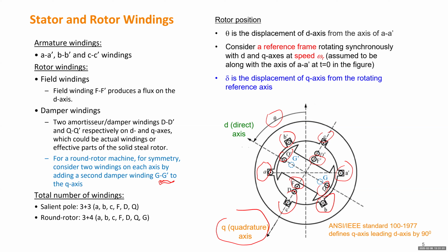But the delta is the angle relative to a frame operating at about 60 Hertz, right? So delta can be positive or negative. If it's faster than the reference frame, the delta will be positive. If it's slower than the frame, it will be negative. So that can indicate the real state of the generator in terms of the rotor angle stability.